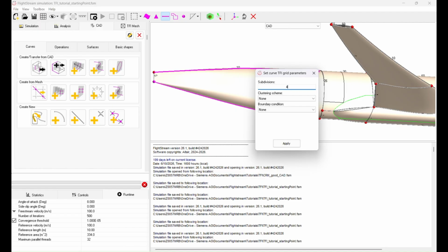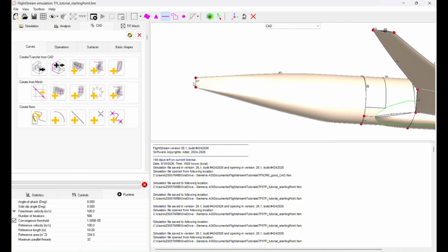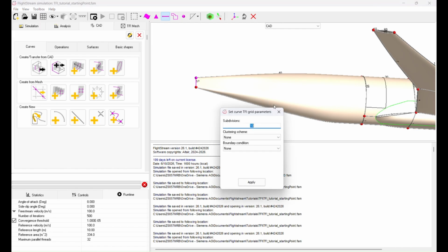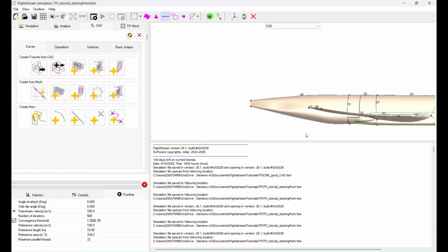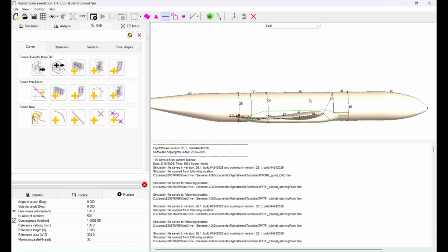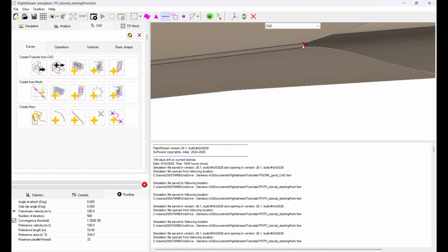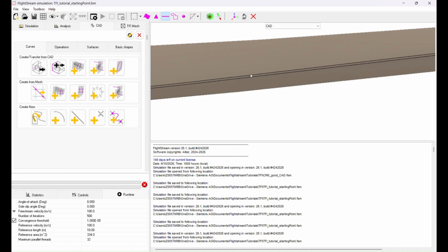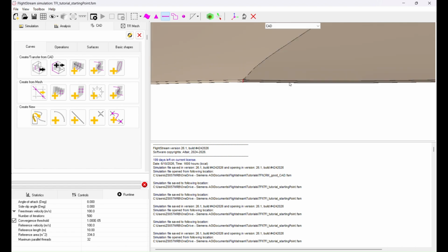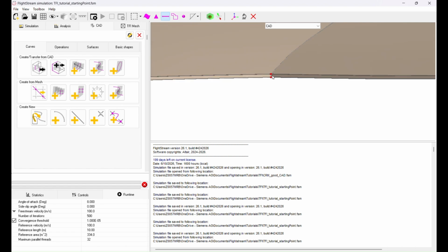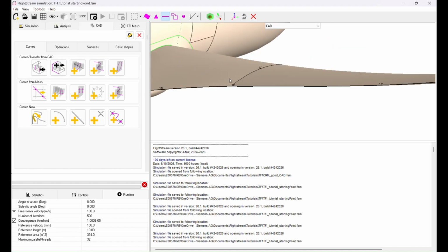We'll finish up the fuselage here, using clustering rates to properly capture our geometry, and then this will become 41 as it's the end point for our panel. Now we're working with our blunt trailing edge. We're going to select each virtual curve that is on the blunt trailing edge and set it to 1 total grid point.